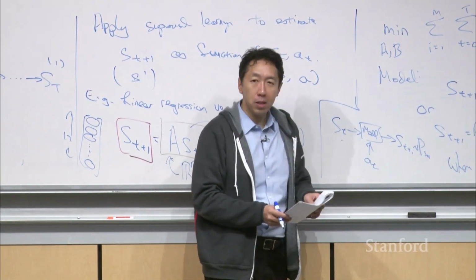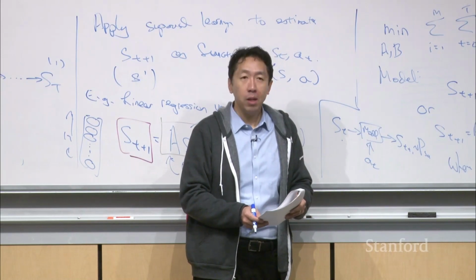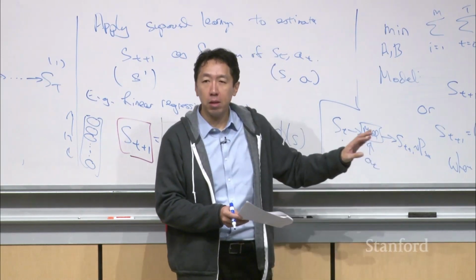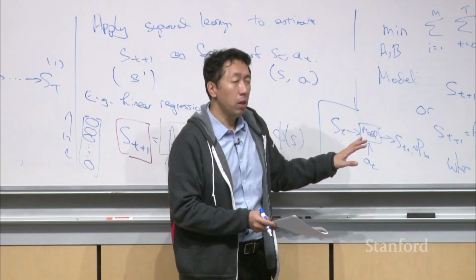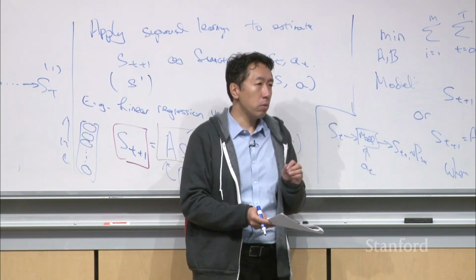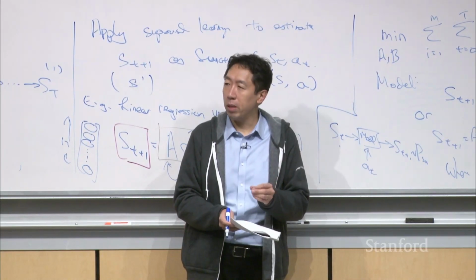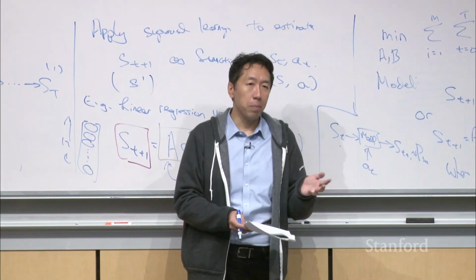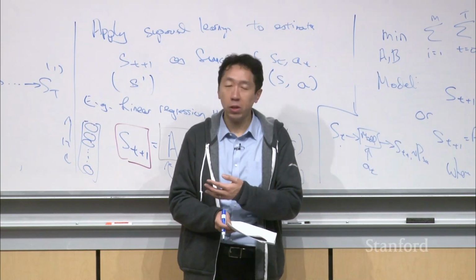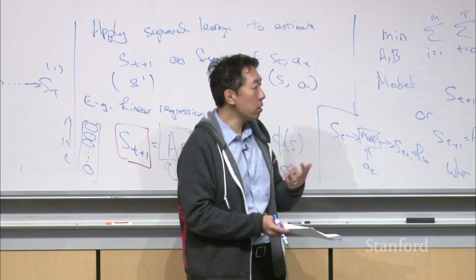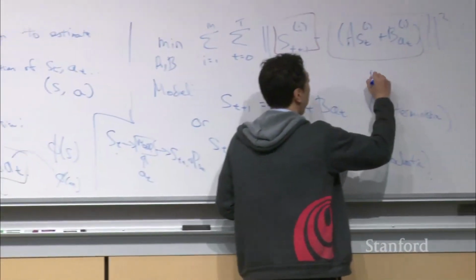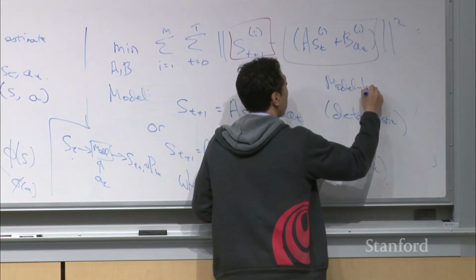So in most cases, when you're building reinforcement learning models, the approach we're taking here is called model-based reinforcement learning, where you build a model of your robot, and then train the reinforcement learning algorithm in the simulator, and then take the policy pi you learn in simulation and apply it back on your real robot. So this approach we're taking is called model-based RL.